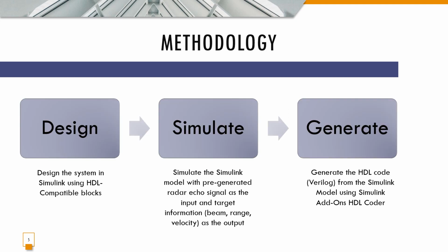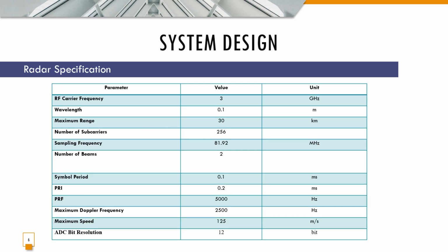And here is the methodology I use. The first is designing the system in Simulink. Second is simulating the designed system. And the third is generating the HDL code of the system using HDL Coder. Here is the overall radar specification, which will be the reference for designing the system.